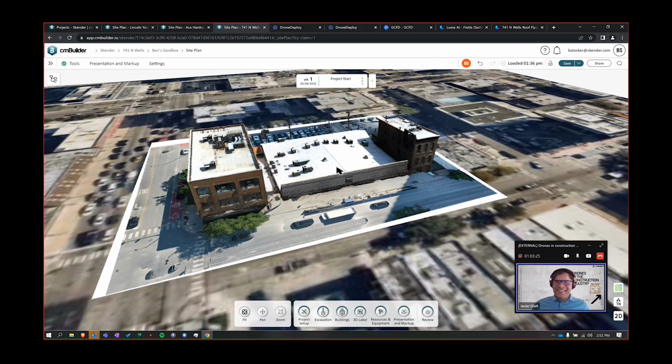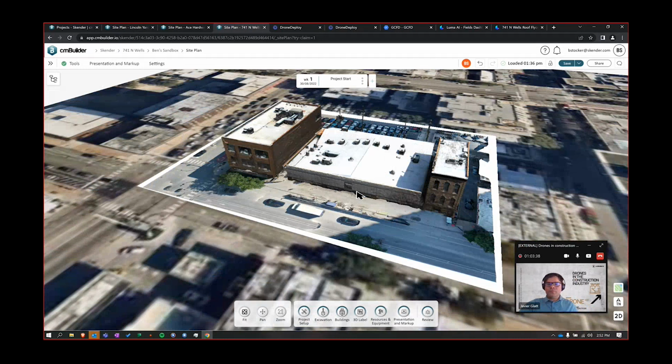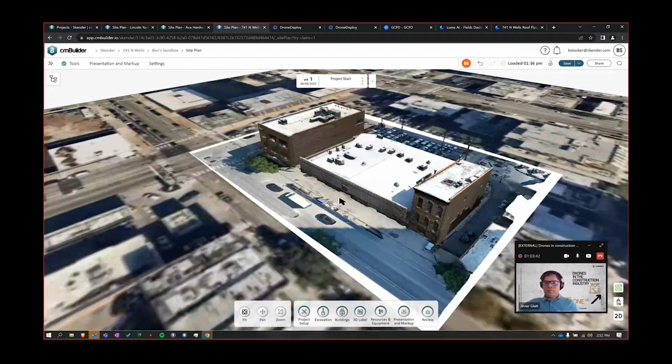Yeah. So my workflow, I bring it into Recap Photo, and it allows me to trim up the model and get rid of noise around the outside of it, and then just convert it to an FBX and bring it into here easily. It keeps all the textures and colors and everything. So just having your photogrammetry models in here provides so much more context too.